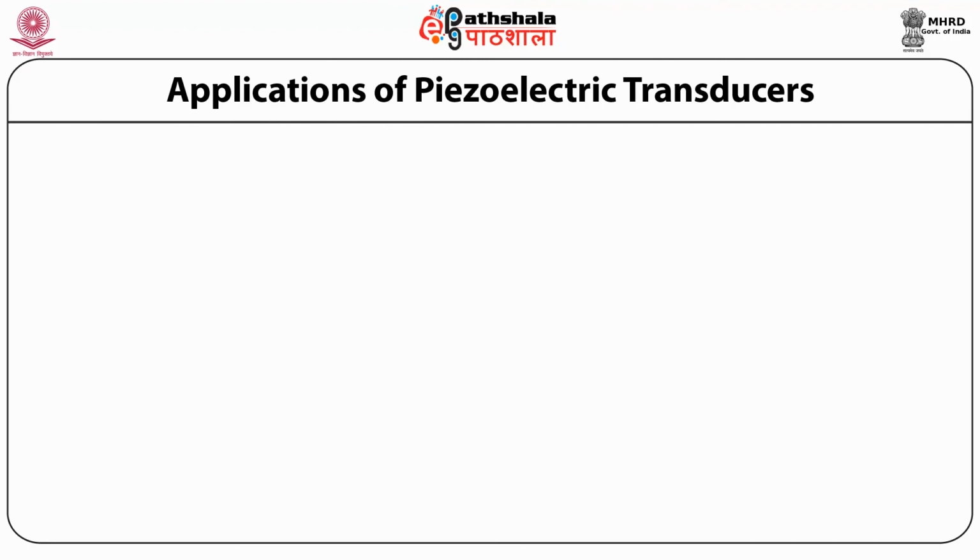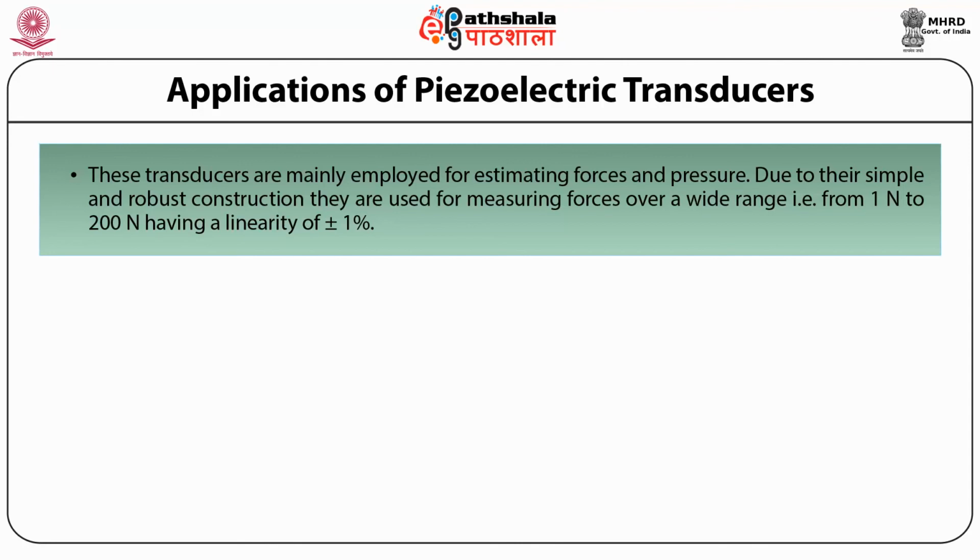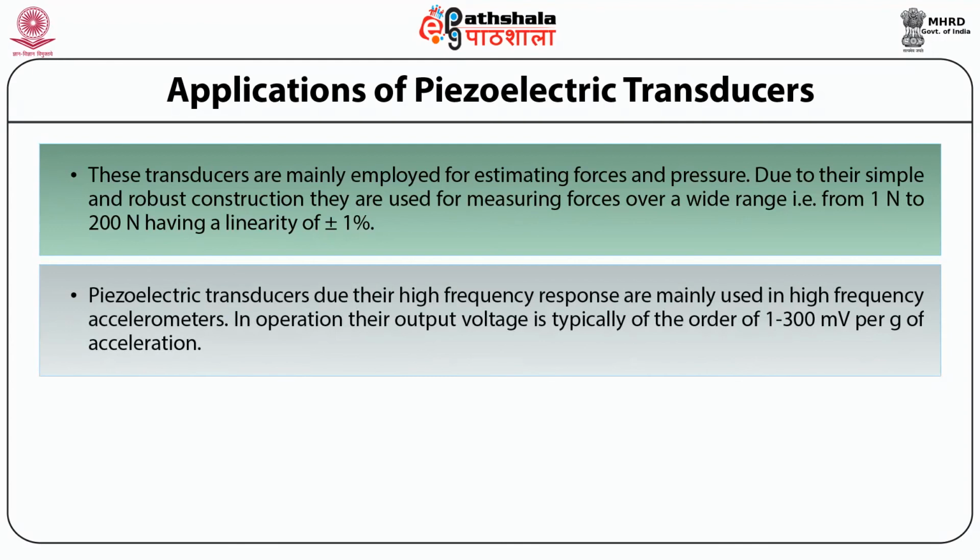Applications of piezoelectric transducers. First, these transducers are mainly employed for estimating forces and pressure. Due to their simple and robust construction, they are used for measuring forces over a wide range, that is, from 1 Newton to 200 Newton, having a linearity of ±1%.